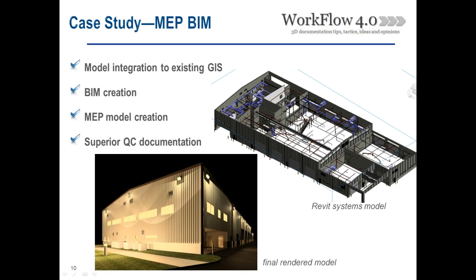They also wanted to come up with a QC documentation plan that would be instituted for all these BIM projects. So we came up with a method of taking reflectorless check shots on the facility as we run our traverse through there, and then doing a local comparison to the cloud to see where that control shot fit in, and how big the data set was with the overlap of the scans at that point in time.